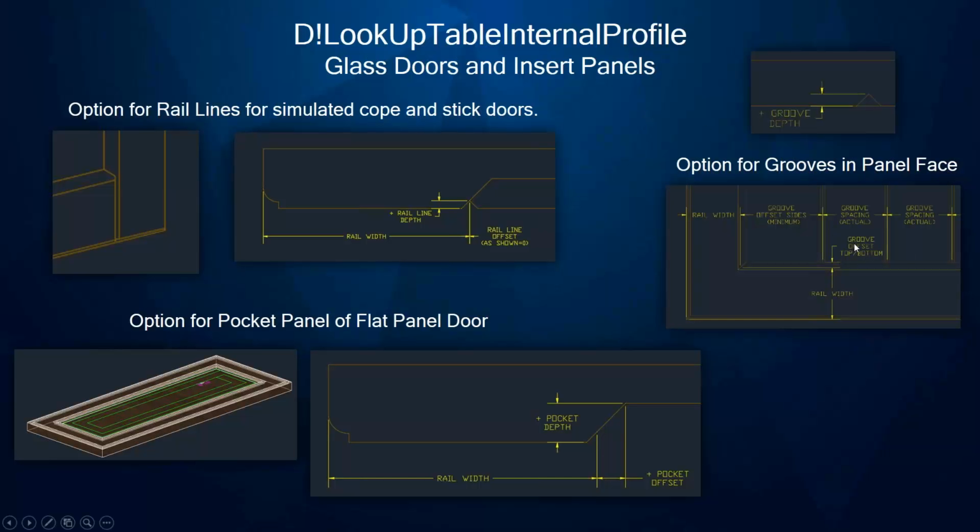There's a groove offset from the end because when you come in with this tool for that groove, if you're using a V-bit, you want to make sure you don't hit the profile there. So you want to make sure that you get that dimension set correctly so that you end up with your grooves showing up correctly on your parts without damaging the inside profile of the door.